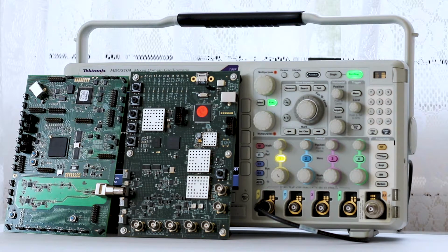Also, it is useful to remove a small working battery-powered AM/FM radio from its enclosure so that signals can be extracted, displayed, and measured, going from the outputs of the power supply and tuner to the speaker. Don't expect to detect a signal at the antenna terminals, but check out the local superheterodyne oscillator with varying frequency outputs as you sweep the broadcast bands.